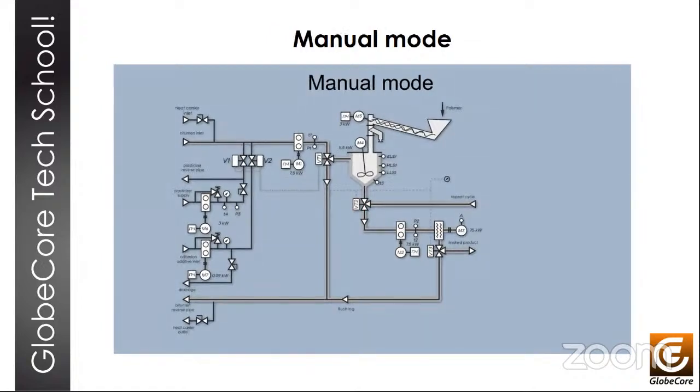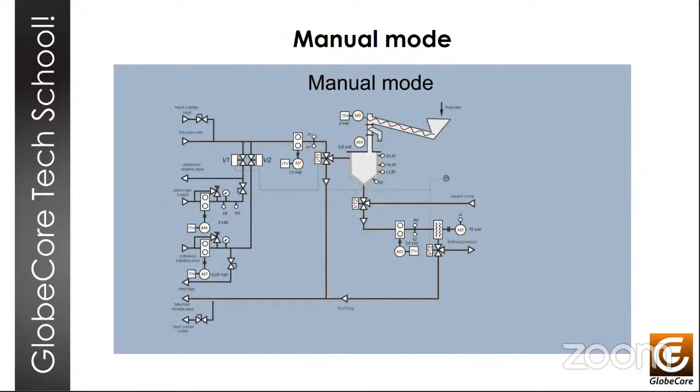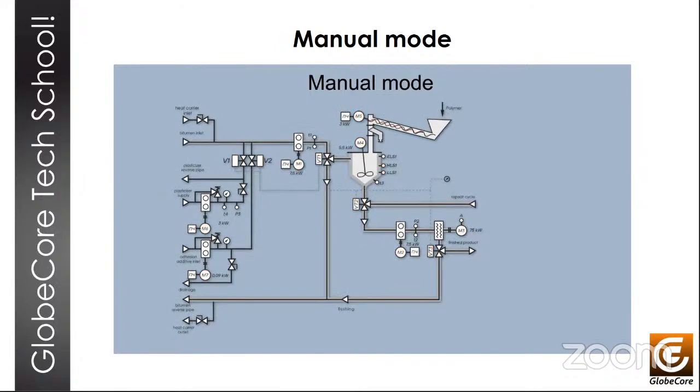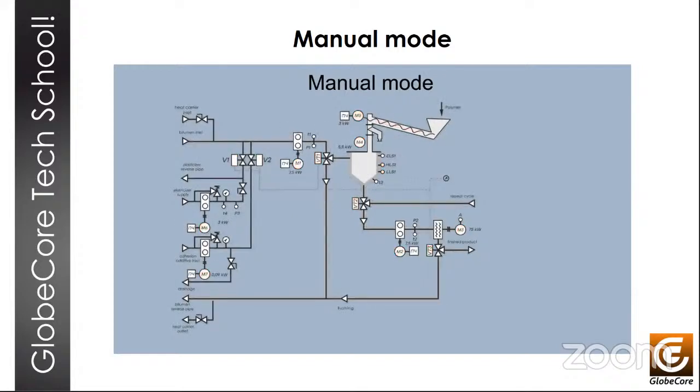And in terms of manual control, this manual mode is used when it's necessary to test operation of individual components of a plant. It's used during startup and commissioning and for adjustments to the process, and if necessary to return the plant to its initial condition if a failure or an emergency stop occurs and we need to reset everything back to what it was. Next slide, please.